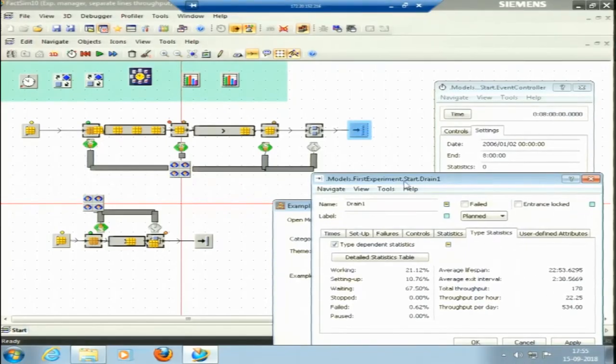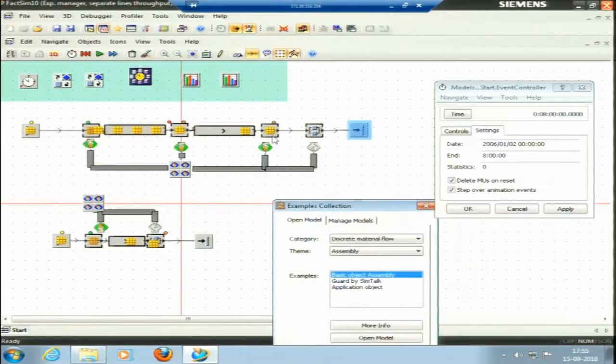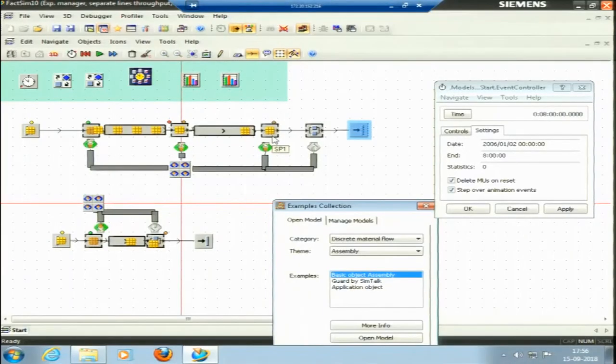This is based upon the inputs that we have given to the specific processes, which I will discuss. It is the setup time, processing time, then the availability: is it available for the complete time, or for 95% or 90% of the time. Then we have the distribution. For instance, if it is a manual process and we do not have much data, only 2-3 data points previously available, we can pick a triangular distribution. If it is an automated process, I can pick a normal distribution with very little variation, because the process is automated. Based upon the inputs that we give, the software will simulate and give us a throughput.